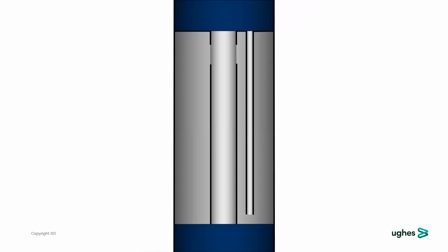By another explanation on that picture, the well fluid will enter the top of the labyrinth chamber, and the difference in specific gravity will cause the well fluid to sink to the bottom. That works because in order to contaminate the next lower chamber, the well fluid must displace a lighter fluid and migrate upward against gravity in order to gain access to the next chamber.